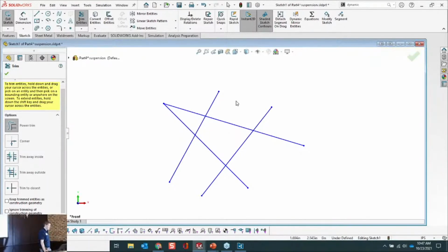If you trim from outside in, it does that trim the closest. It does that corner trim. But what many people don't know, let's say I'm trimming like this. Well, if you're holding in the left mouse button like I am, you guys see that red dot on my screen? Well, this trim allows you, if you accidentally do something, to do this thing I call red dot reverse. So if you're in here and you're doing a trim and you're going nuts, well, if you accidentally go too far, you can see the path that you used to trim, and if you go back to that red dot, you can put items back in there.